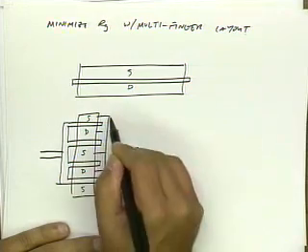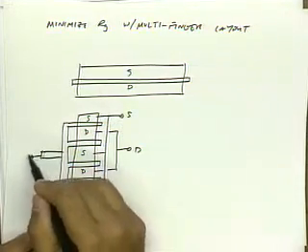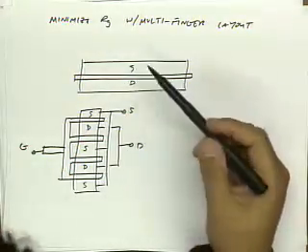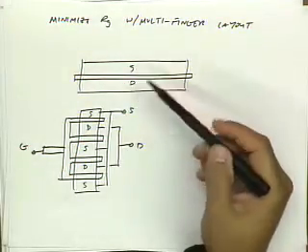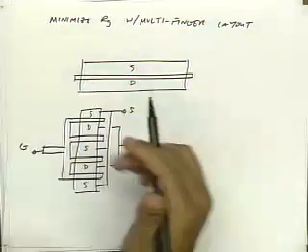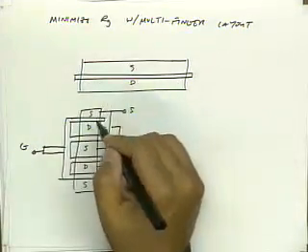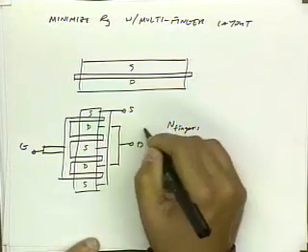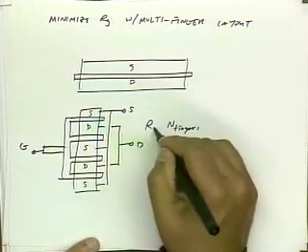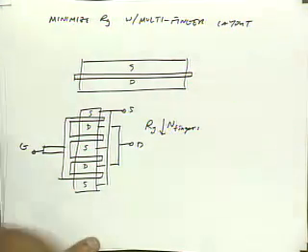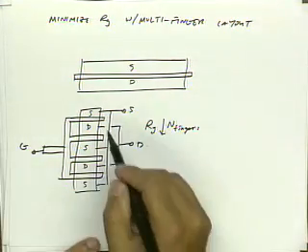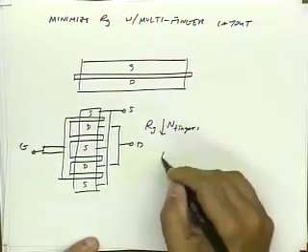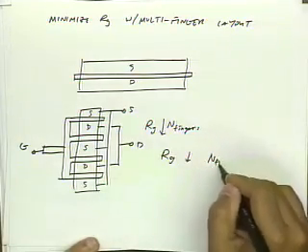So this is my drain junction, this is my source junction, and this is my gate. And you can see this has a twofold improvement, because not only am I reducing my gate length by n, so if I have n fingers, so our gate resistance goes down proportional to the number of fingers, but since these are now in parallel, I get another factor improvement. So our gate resistance goes down like n fingers squared.